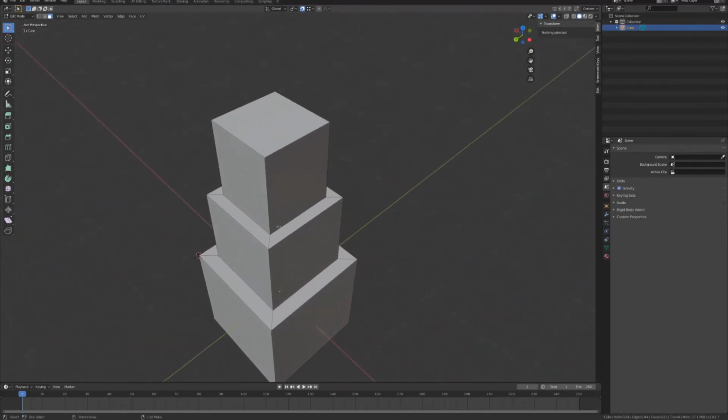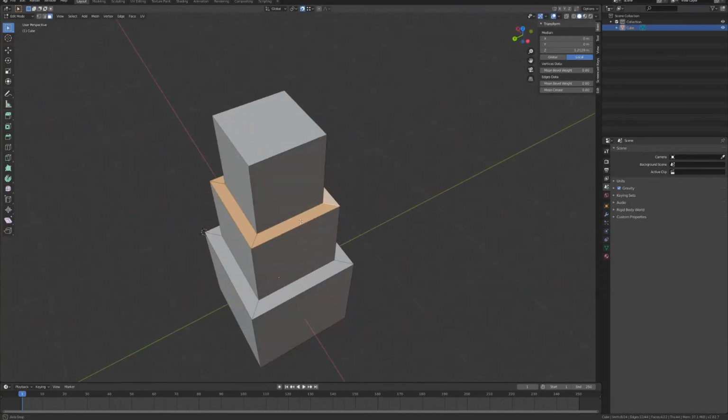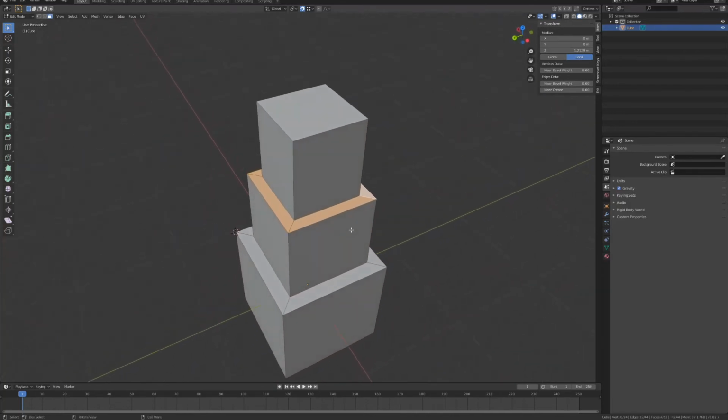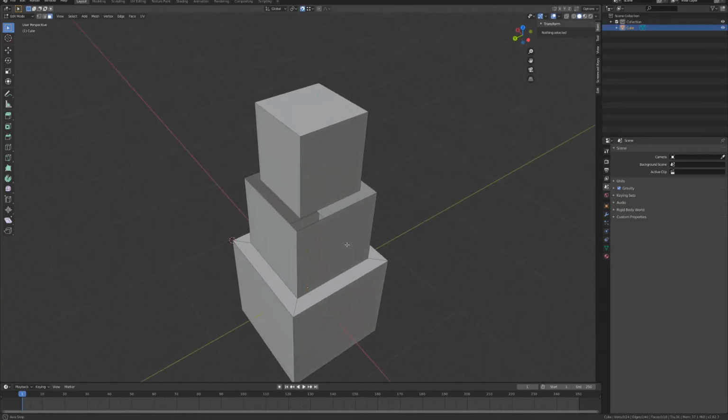So, what you might want to do, which some of you might have already seen, is you want to take these faces and you want to delete them. To delete faces, or delete vertices, or delete edges, you press X. It opens up this menu, and it also allows you to dissolve, by the way, which I will be covering slightly later. And you can delete those faces.